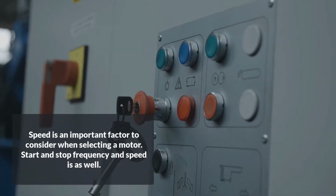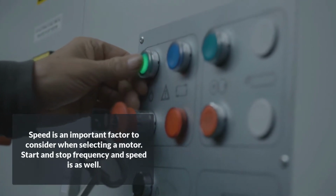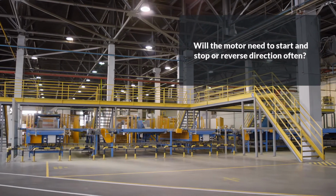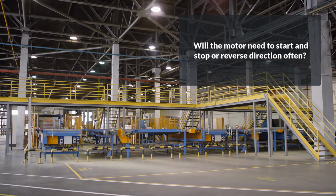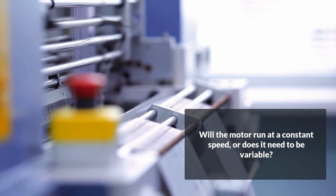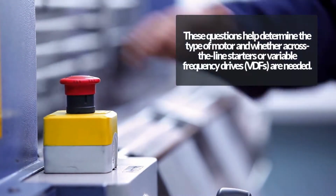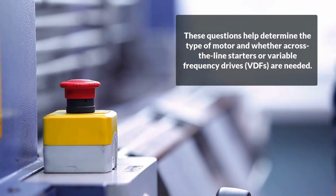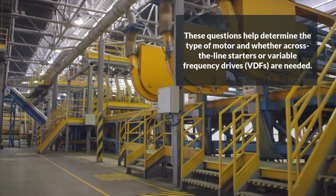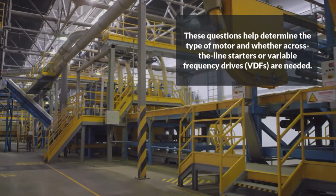The speed of a motor is always part of the motor selection discussion, as is an application's need for frequent or fast starts and stops. Will the motor need to start and stop or reverse direction often? Does it need to do so quickly? Will the motor run at constant speed, or does it need to be variable? The answers, in addition to determining the type of motor needed, such as an inverter duty AC motor, help to determine if across-the-line starters or variable frequency drives are needed.